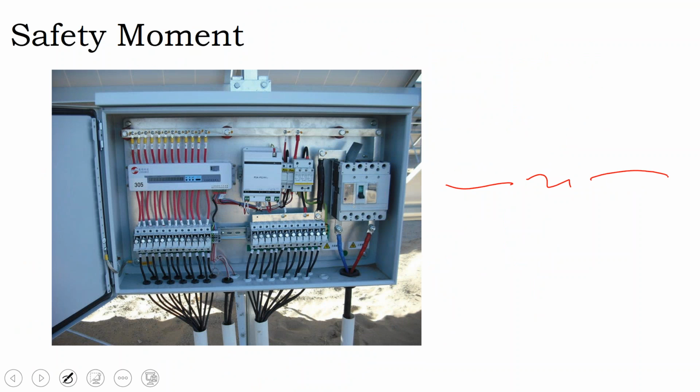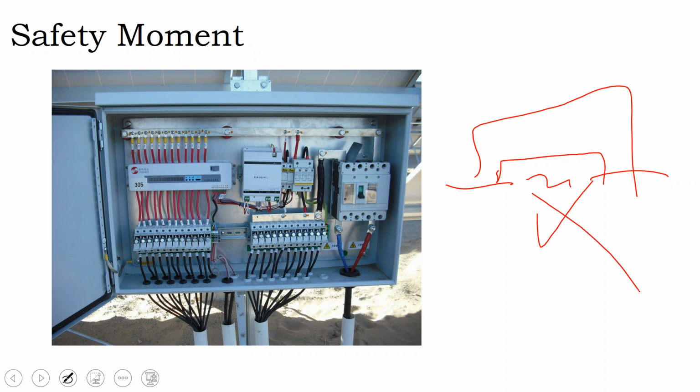Now, it might be that it's just a little bit of arcing, and most of it is a continuous connection. With your older inverters that did not do arc fault detection, you would still get current across it. They weren't detecting the arc fault, so there was an error, but it wasn't reading it, and that gave solar almost a feeling of being bulletproof, because you get all these amateur installers out there making bad connections, but it doesn't really impact system performance upon commissioning. It's not a big problem yet. It's not impacting your performance. The inverter doesn't see the error, and so you say, well, solar has no errors and it's super easy.